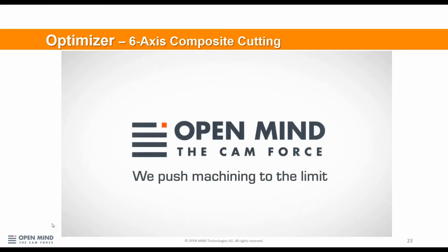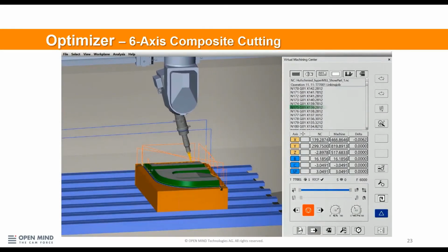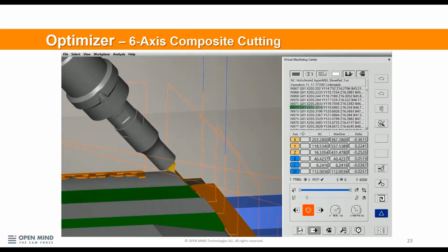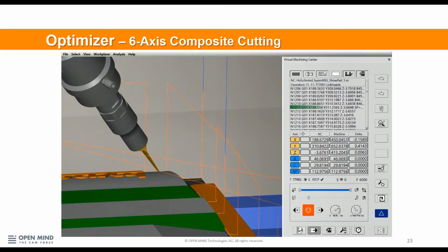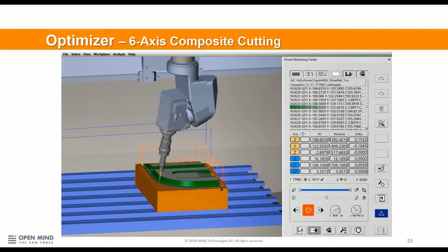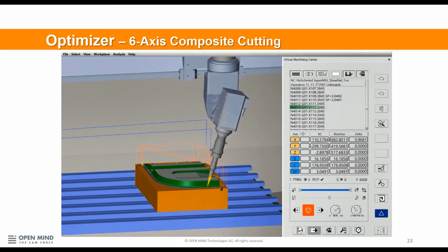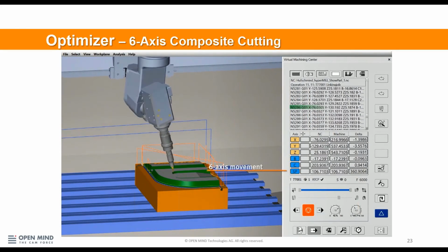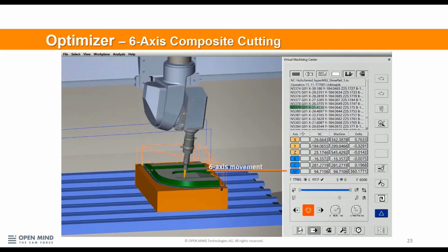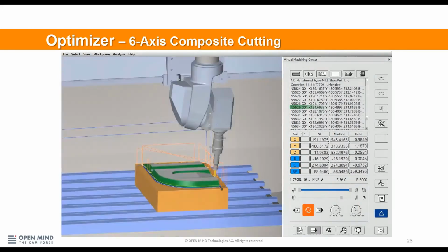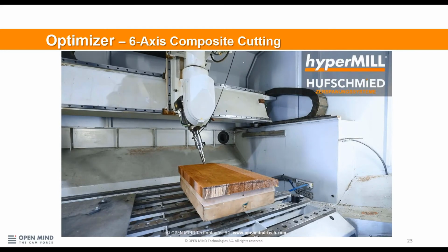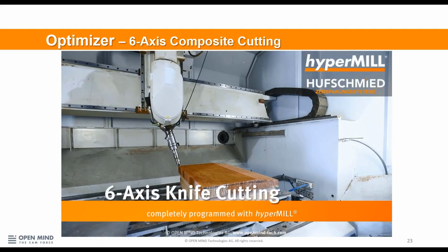This is a presentation of 6-axis knife cutting for the cutting of honeycomb composites. Composites are a high-performance, lightweight structural material. They're crucial in aerospace applications where performance is measured by weight reduction. The cutting process is primarily trimming shapes with a swarf toolpath. This material is best cut with an ultrasonic knife.